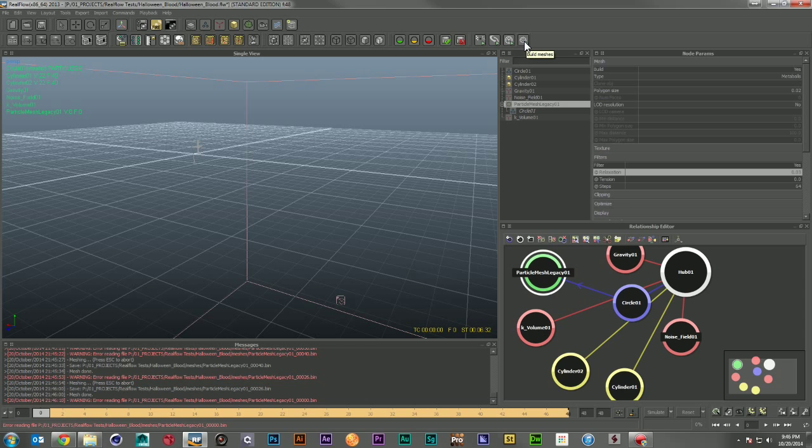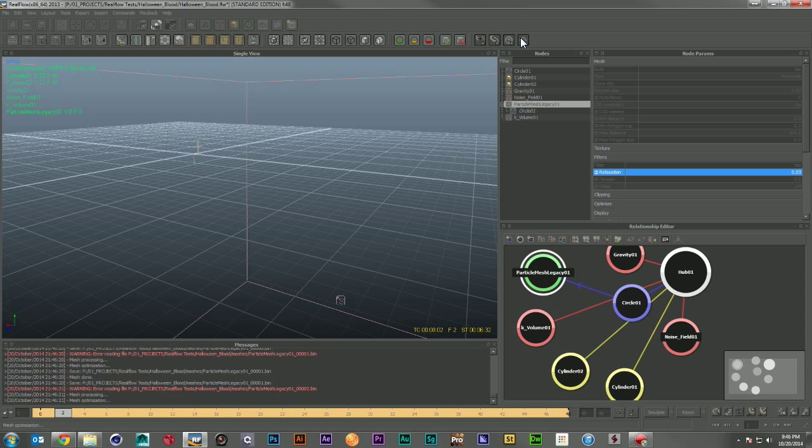So let's go ahead, rewind to the beginning, and I'm going to come up to the top and click my Build Mesh button. And I want to make sure that I have my mesh highlighted when I hit it. So I'm going to click on the Build Mesh, and it should run through fairly quickly. No frame is going to take much longer than the ones we saw. So I'm going to let this run through, and then we're going to give it another look before we bring it into the 3D world. All right, I'll see you in a bit.